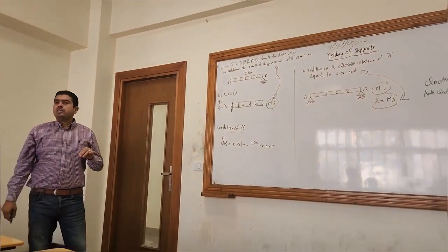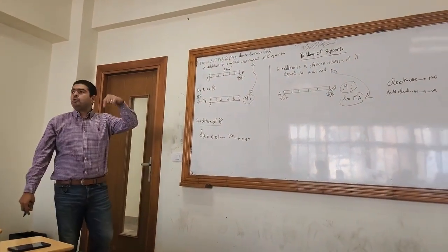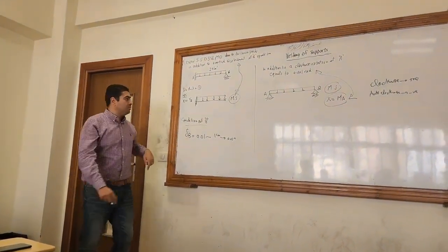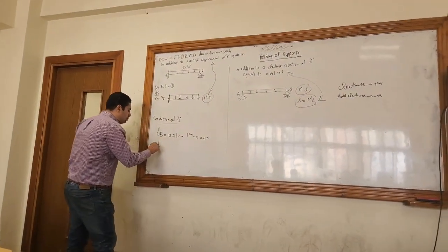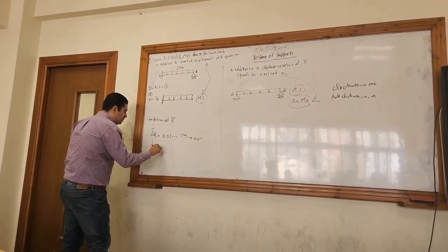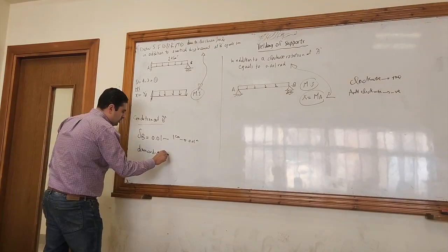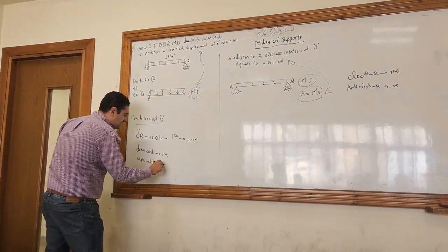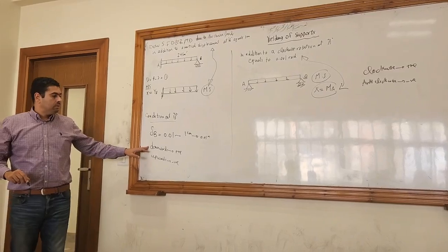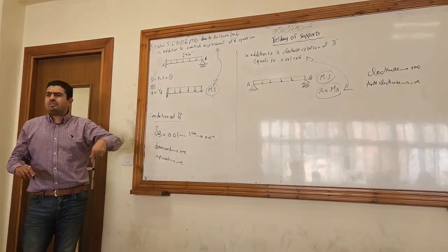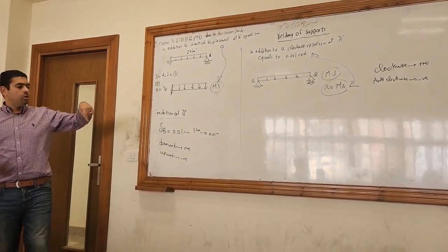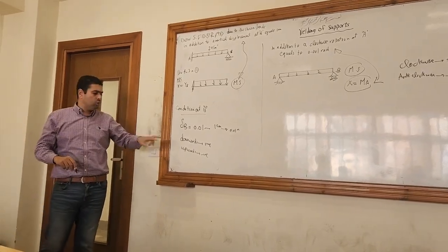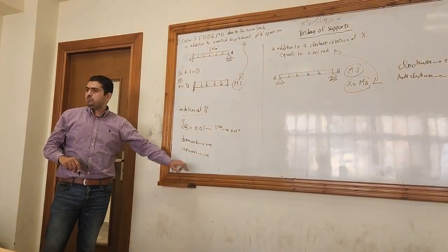If it's downwards, this is positive. Downwards is positive, upwards is negative, because the normal deflection is down. This is the normal one, so that's why we give it the positive. It's not normal for the point to move upwards, so we give it the negative sign.